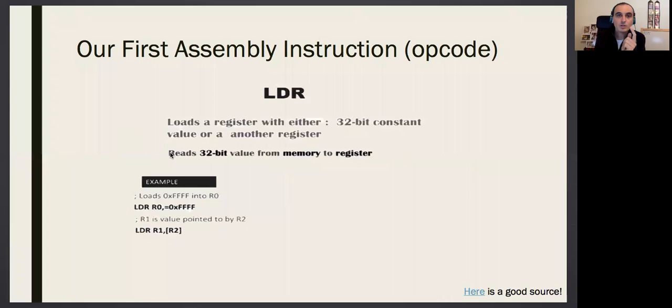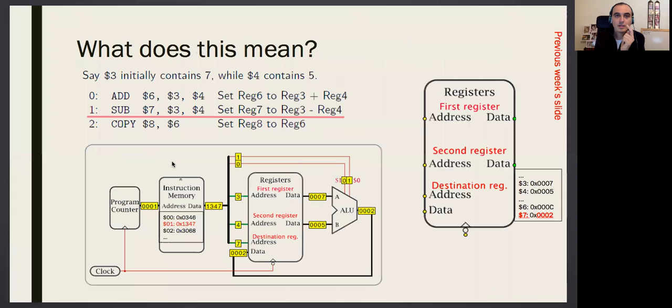You remember, the processor is executing the program one line at a time. It's executing this one, then the program counter moves to this one, then this one. So the clock is changing the program counter. But imagine there is another mechanism changing the program counter. Its program counter is pointing to 03 and it's just executing something. At some moment, I say, hey, program counter, go back to 00. It will be jumping to 00, so it will be like a jump in my program.